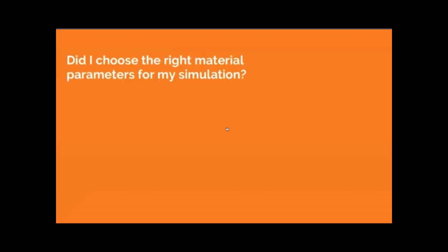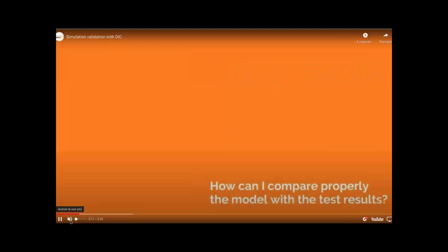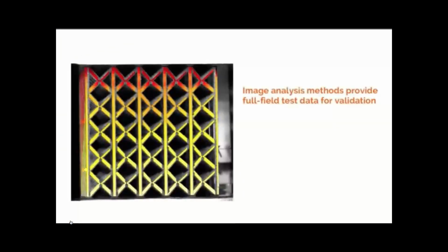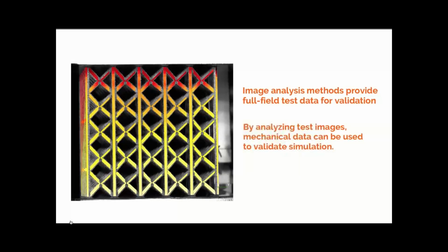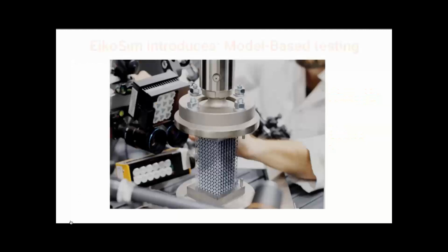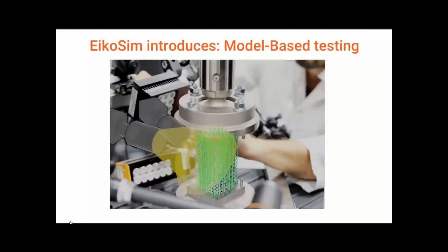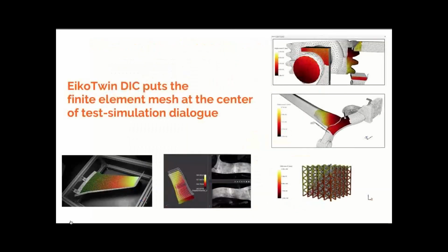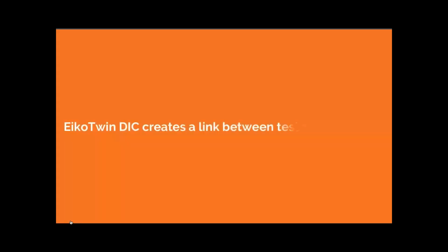Well, these are the questions that simulation engineers are usually asking us or wondering about. So in order to do that, we built a tool that answered this question of simulation confidence and trust, which is central in our approach. And the idea here is to have that kind of measurement, which is not a point-wise measurement. It's a measurement that's taken from the cameras to the mesh, and in order to have usually thousands of measurement points. And all of the color fields that you see here, they're expressed on the mesh, of course, but they're measurements. They're displacement, strain measurements.